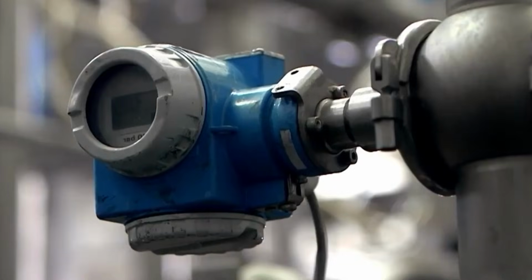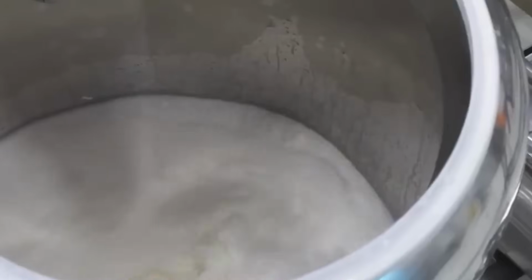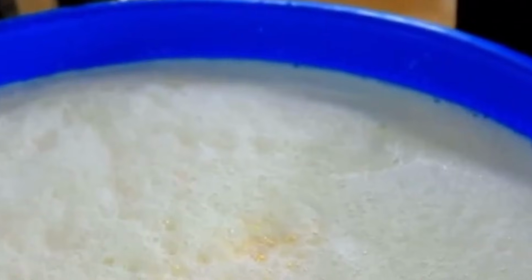Forming and portioning depend on the packaging format. For cups and tubs, rotary or piston fillers dispense the frozen yogurt into containers on an indexed conveyor line. Fill levels are verified using laser height sensors or load cells beneath the filling stations. The containers are then lidded using pick-and-place robots, followed by heat sealing or snap lid application depending on the package